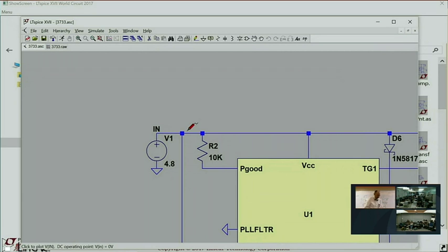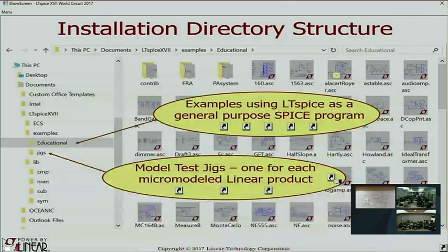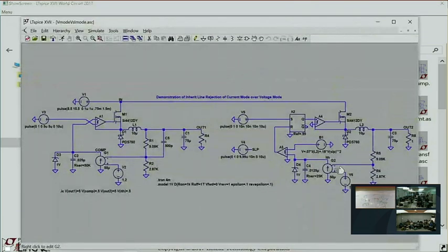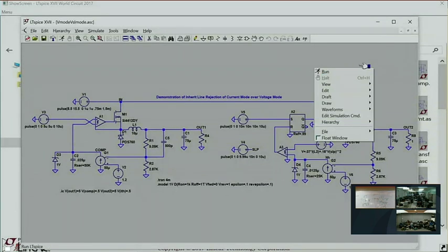Anyway, I have a little example here that you might find interesting. So here, this circuit is that circuit. That's a voltage mode controller. There's the comparator. This circuit is that circuit. That's the flip-flop. And I'm going to hook them both to the same input, and I'll have the input voltage step from 8.5 volts to 15.5 volts. Let's see what the output voltage does.